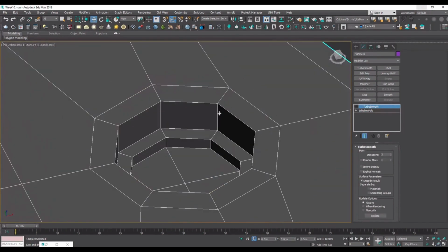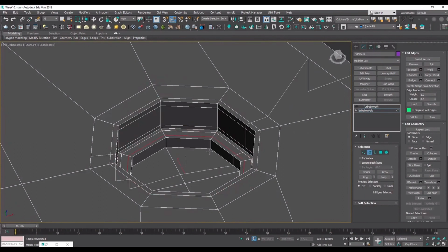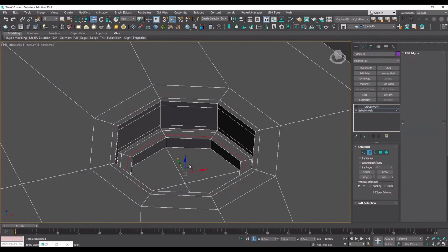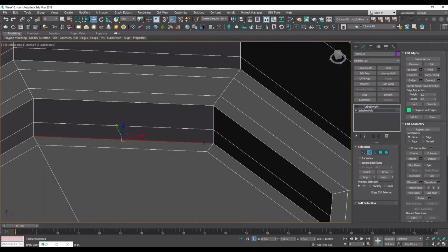And again, by using the Swift Loop command in the edit menu, I'm going to now just add the extra edges and supporting edges to get what I want and preserve the sharpness that we talked about. And now I get an inset from the surface that I have, and just in case, for here, I'm going to add another edge loop.